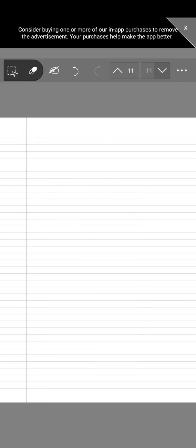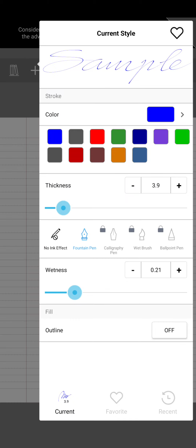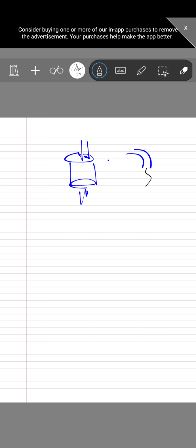So if this is the specimen which is being clamped here somehow, and we have grooved ends, and we lubricate these grooved ends with some oil to reduce the friction, the grooved ends will hold the lubricant for a longer time. So that's how we can reduce the friction.